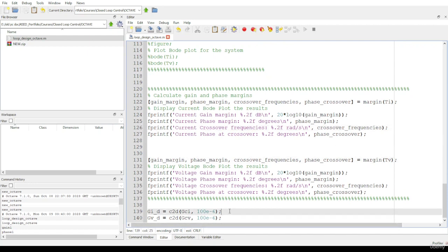And now this next part is very important. It's absolutely crucial. In closed loop control systems, you're basically updating the duty cycle in intervals. In this case, I was updating every 100 microseconds. Of course, you could go as low as the nanosecond ranges, but in that case, you really need to optimize your code for that particular function. In this case, I used a lot of floating point values, which took a lot of time, but I think it worked out all right for this particular scenario.